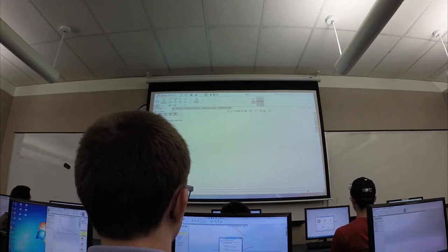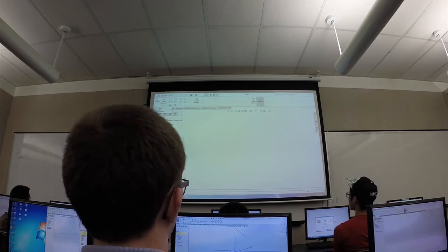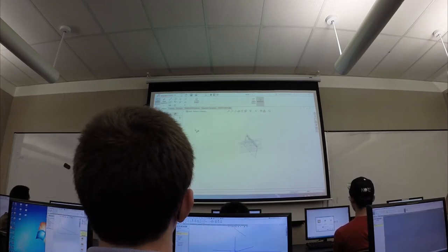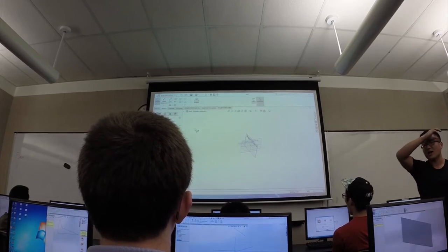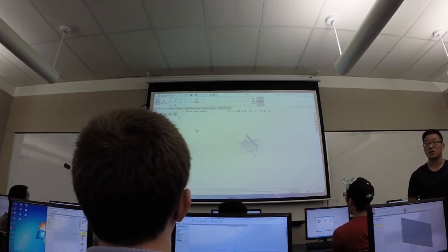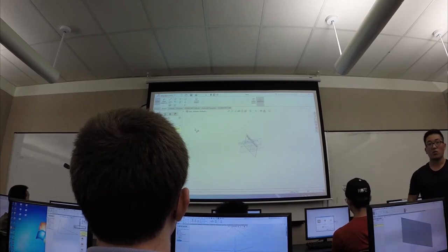So we're going to open up a 2D sketch. So just on the drop-down menu, just click Sketch. So the first thing that it has you do is selecting a plane. So you can't draw a line without referring to a plane on a 2D sketch, right? The software has no idea what point in space you want to draw that line.